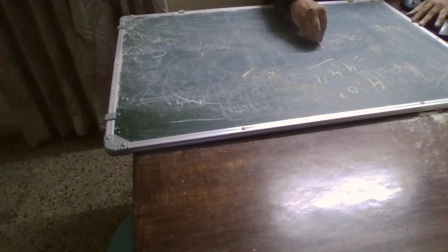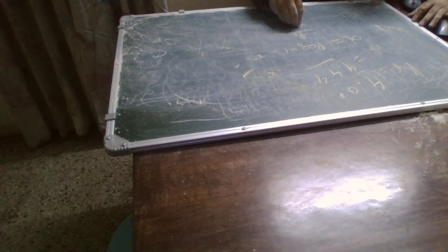Okay, so the regulation and the power handling ability of the core we can very easily relate by some constant. Let's say alpha is the regulation constant in percentage, and that is basically going to be equal to power upon twice Kg Ke, and the constant Kg is basically determined by the core geometry, and the core geometry I will take separately.